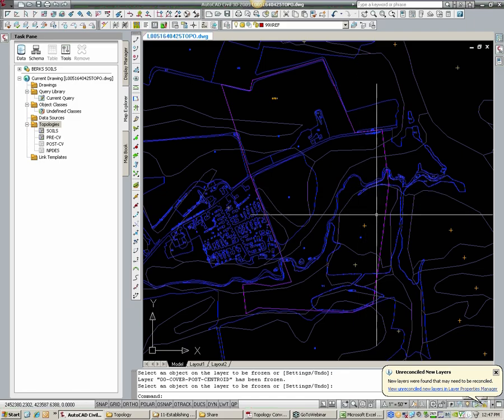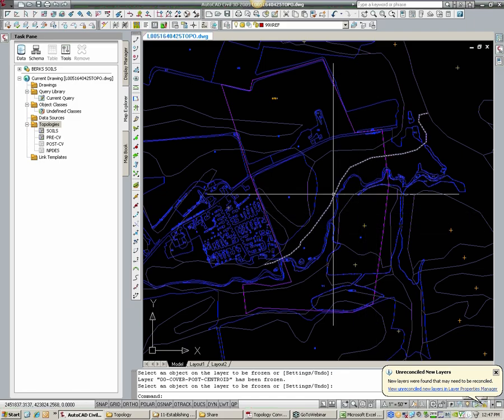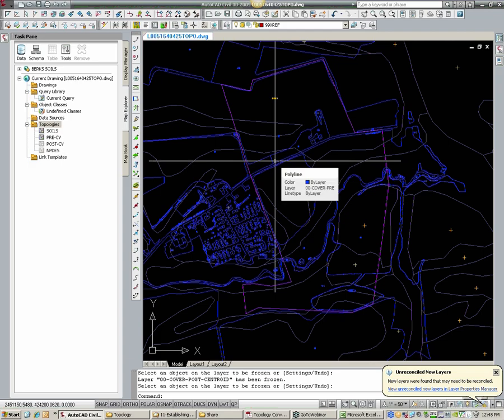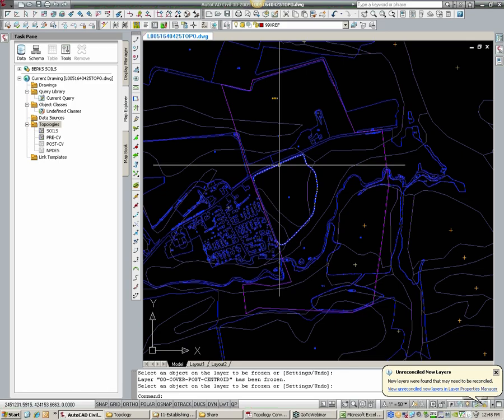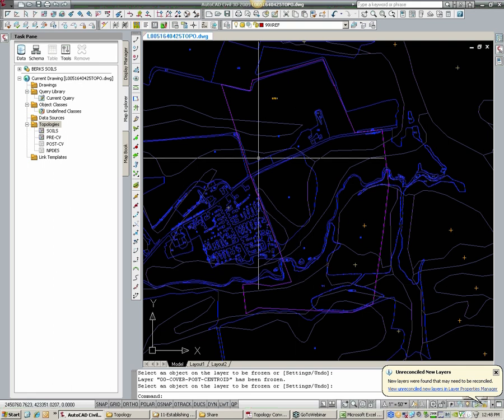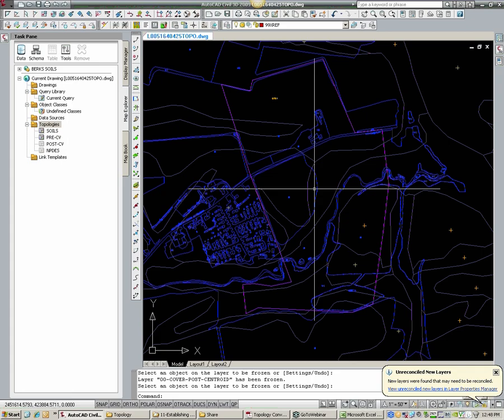So I need to overlay this area with all the soils, with all the different covers, which is a big task. It's a lot of tracing around polylines. And it will take a good amount of time, and you're not building anything. Granted, making this pre-development, I didn't really need to actually do all this. All I really needed for my pre is within this area here. That would still take some time, but not nearly as much as it would to trace all the soils out. And then if anything changes, I have to do it again, especially in the post condition.